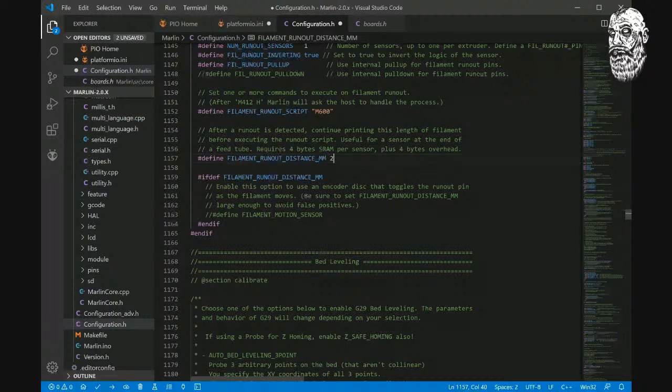on a printer with a Bowden, but on my printer with a direct drive extruder, basically the end stop will trigger inside the hot end, telling you, hey, the filament ran out, but it'll run for 2 more millimeters just in case it's not a false positive. And with those 2 millimeters run, if it's still open, it'll then enforce the M600 filament runout script. So that is your magic. That is how I like to set it up.